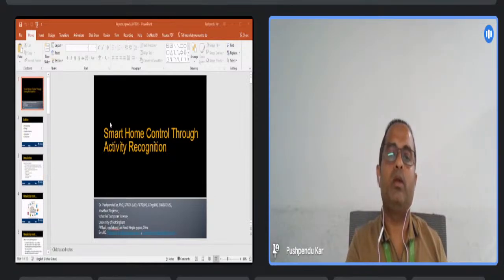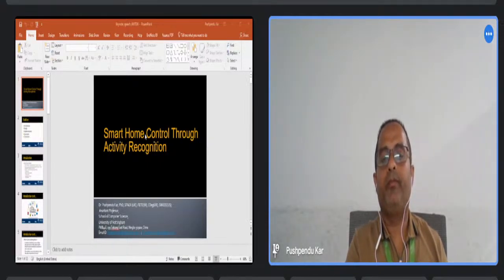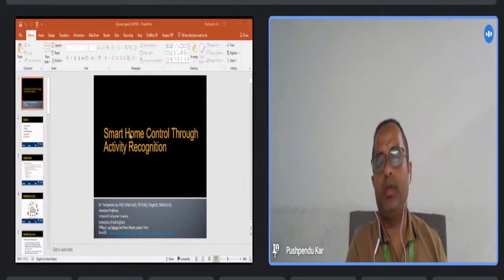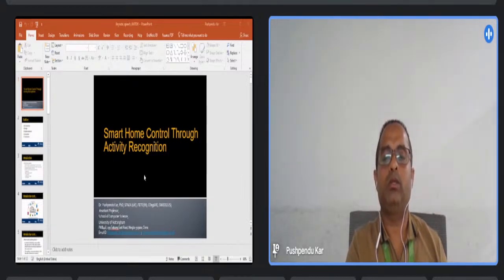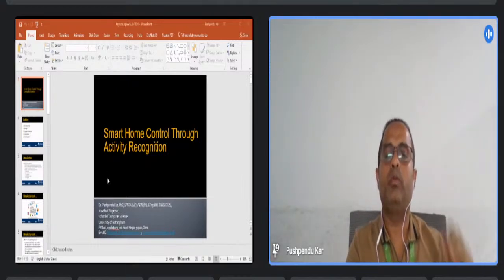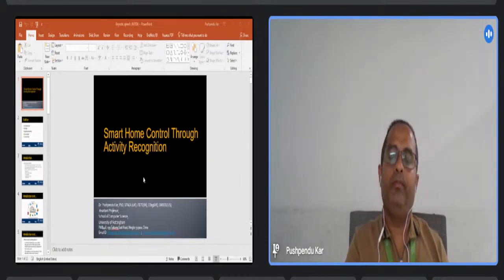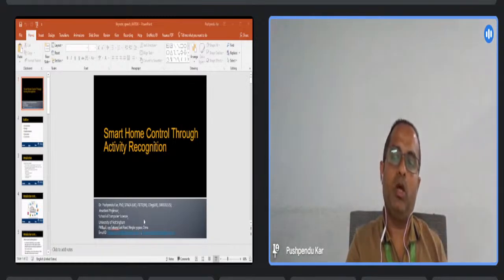First, the infrared sensor, that is the Grid-EYE sensor, identifies the presence and location of the occupant inside the smart home. Then if an occupant is present inside the smart home, the system reads the information from the acceleration sensor. This acceleration information is sent to the microcontroller MCU, and the MCU processes the acceleration data and sends it to a computer.